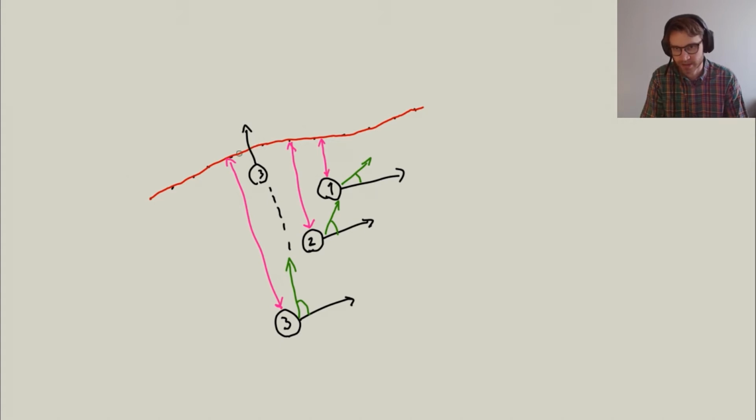And now that it's facing straight at the path, what it will lead to is this type of behavior that might stabilize, and then it will go with the path. But this results from the sort of pursuit of trying to get to the point that is right next to the turtlebot.